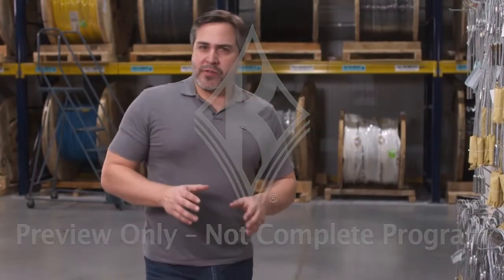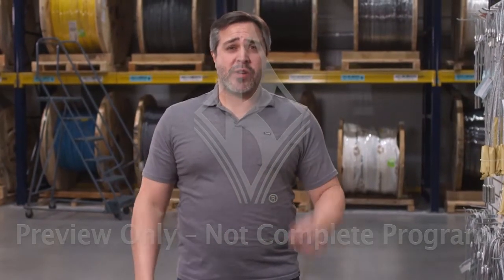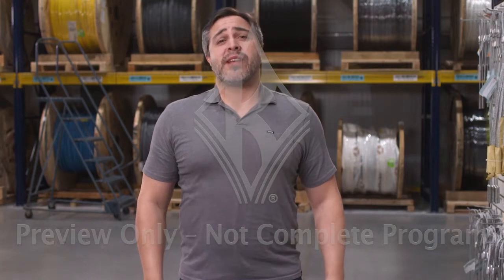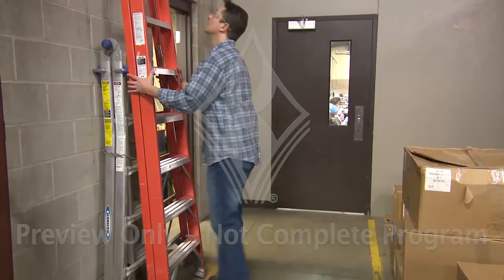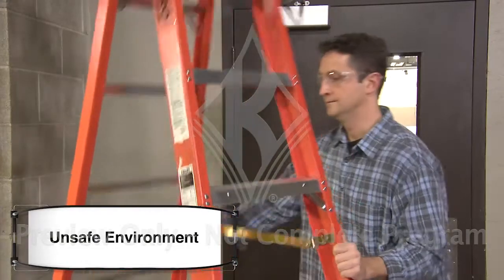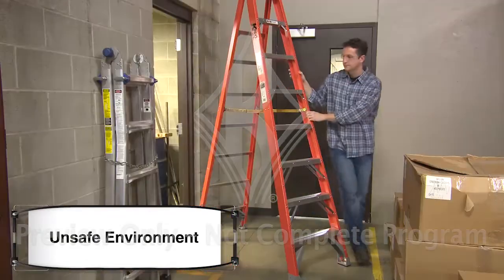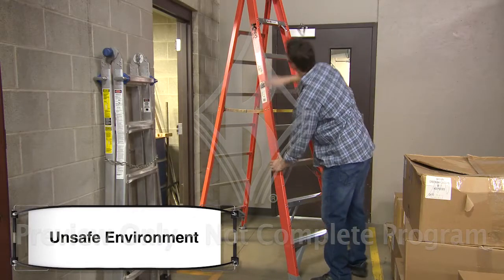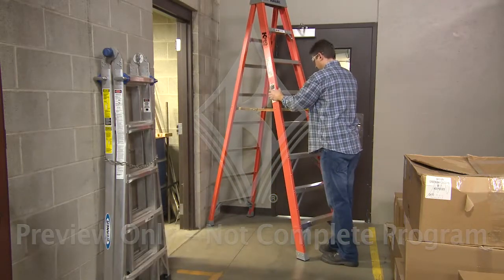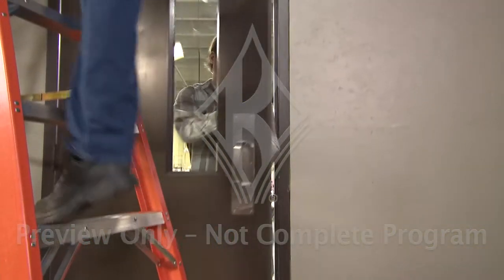In order to reduce the risk of injury, it's important you're aware of situations that can pose potential hazards when working with ladders. There are three main types of hazards: unsafe environments, unsafe equipment, and unsafe behavior. Many times, it's the environment that creates the fall hazard. In this example, the worker inspects the equipment to make sure it's safe before use, but the environment itself creates a hazard because the ladder is in front of a door. By not barricading the area, this worker puts himself and others around him at risk of injury.